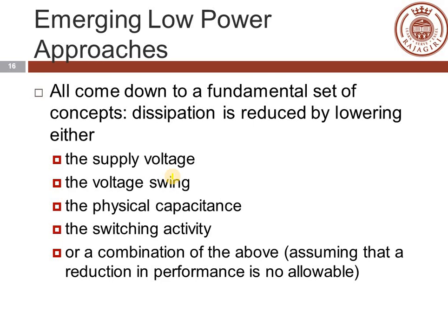So before winding up this session, we will have a summary of what we had today. We started with the need for low power VLSI chips. Then we saw the mechanisms of power dissipation inside digital CMOS circuits. Those mechanisms are static power consumption and dynamic power consumption. The contributors of static power consumption were substrate current, reverse bias junction leakage current, and pseudo NMOS circuits.